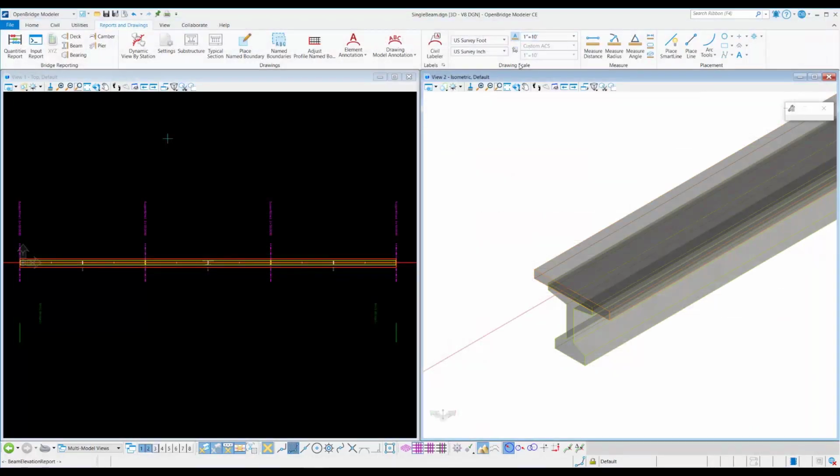For this example, I used precast beams, but the single beam option is applicable with steel girders as well, whether they are rolled shapes, built-up sections, or steel tubs. Single beam bridges can also be created using the bridge wizard by specifying the distance to the left deck edge in the beam spacing field.